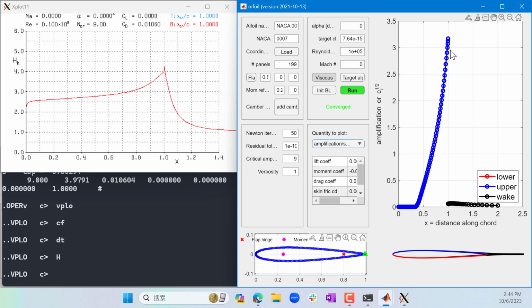So the consequence in designing and analyzing airplanes and other things is that if your drag is dominated by flow separation, you want turbulent boundary layers, because turbulent boundary layers don't separate as easily. If your drag is dominated by skin friction, you want laminar boundary layers, because laminar boundary layers have less friction. So that's the only 2 things we are going to stress, not now yet, but later.